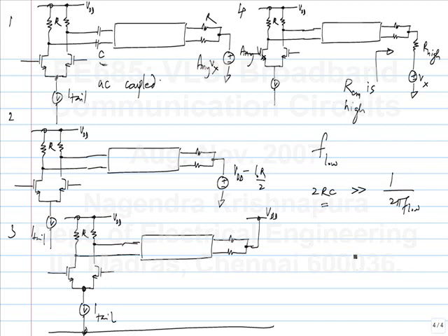These R values are typically small, because here we are talking about terminating transmission lines. So what's a typical R value? 50 ohms, 25 ohms. Usually it's 50 ohms, but in any case, what is the highest value of transmission line impedance you can have? 377 ohms.